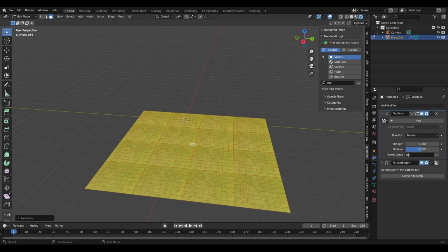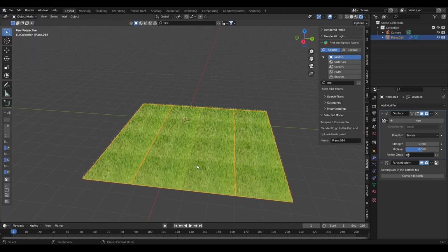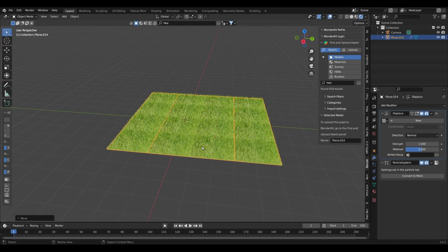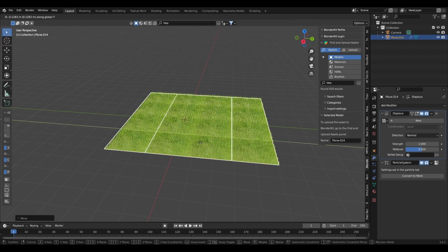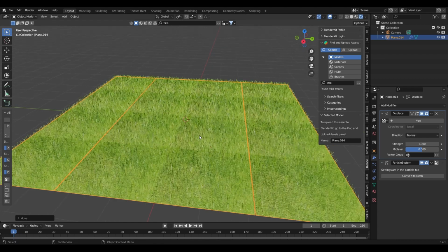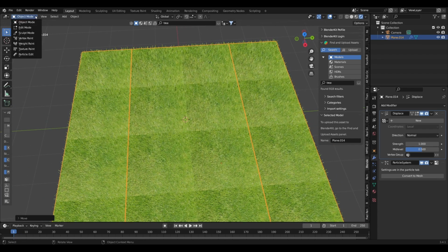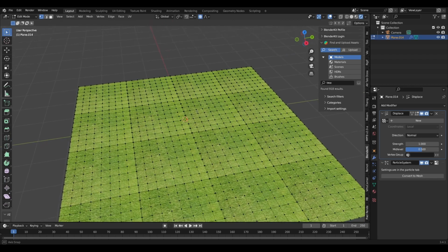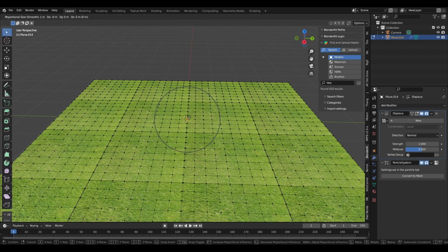and we're gonna do what's called proportional editing. Hold up, and go back to object mode. Just move this down a little bit so I can just kind of do a dead center, or at least as close to dead center as possible. Now we're gonna do it. Okay, editing. You click your proportional editing. We're gonna select vertice, that one in the center. If you press G and Z, as you see, we're getting our hill here.